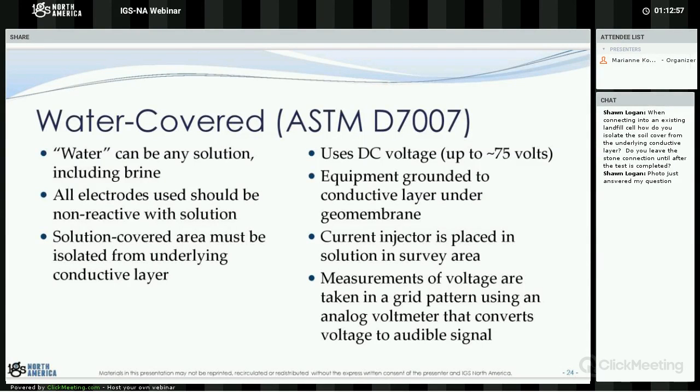So, you know, some stainless steels are going to react with salts, so you need to figure out an electrode that's not going to react with whatever that material is. Every chemical reaction is just an exchange of electrons, right? An exchange of electrons is a differential in voltage, so it will throw off your voltage measurements.